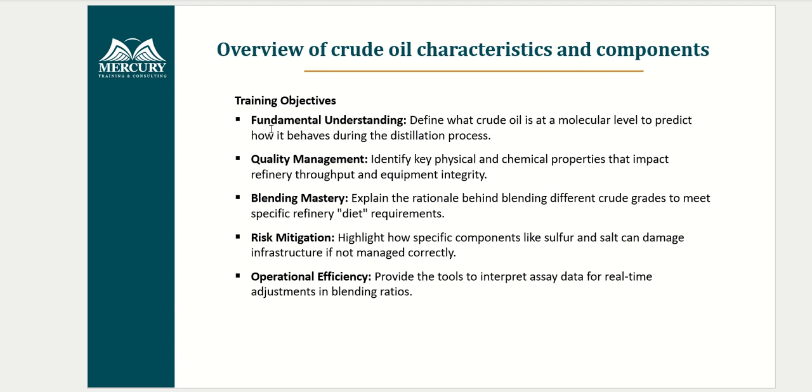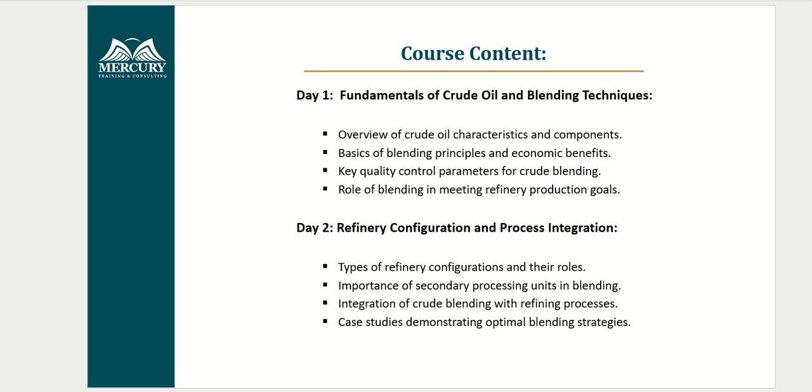The training objectives were fundamental understanding, quality management, blending mastery, risk mitigation, and operational efficiencies. On day one I covered fundamentals of crude and blending techniques: an overview of crude oil characteristics and components, basics of blending principles and economic benefits, key quality control parameters for crude blending, and the role of blending in meeting refinery product goals. So it starts with the fundamentals and then becomes more advanced.